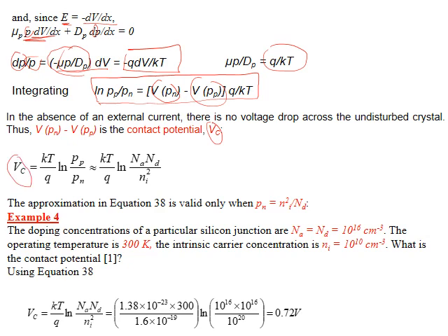So this gives me the voltage on the contact at the end, because don't forget, photons come to the cell and produce electrical current. This electrical current should be collected by fingers and taken to the bars, and the bus bars at the end are connected together to come up with only two terminals, positive and negative, representing the output of the solar cell.